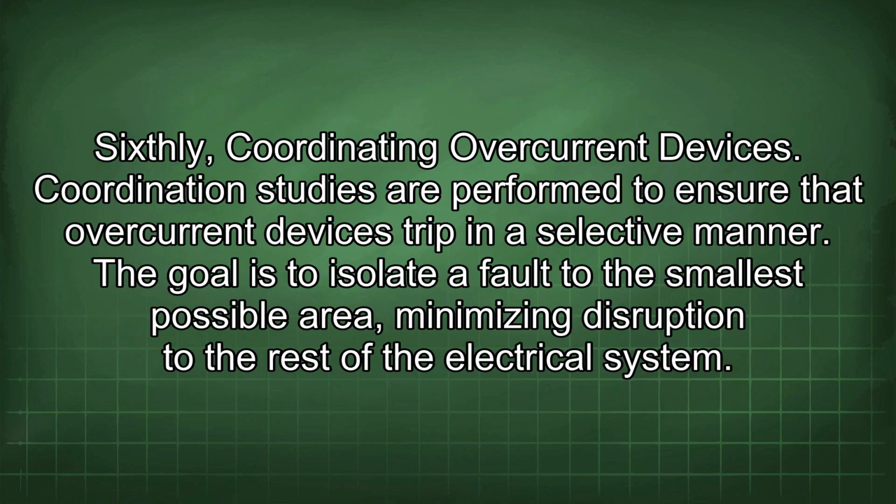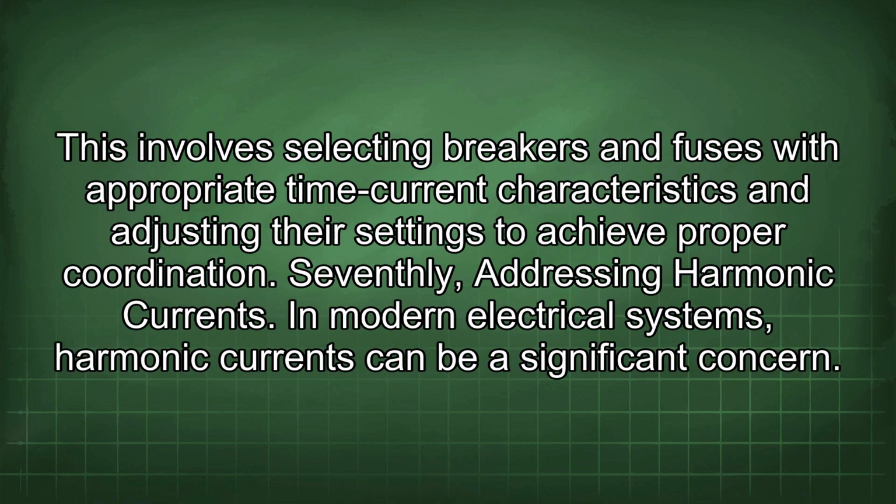Sixthly, coordinating overcurrent devices. Coordination studies are performed to ensure that overcurrent devices trip in a selective manner. The goal is to isolate a fault to the smallest possible area, minimizing disruption to the rest of the electrical system. This involves selecting breakers and fuses with appropriate time current characteristics and adjusting their settings to achieve proper coordination.